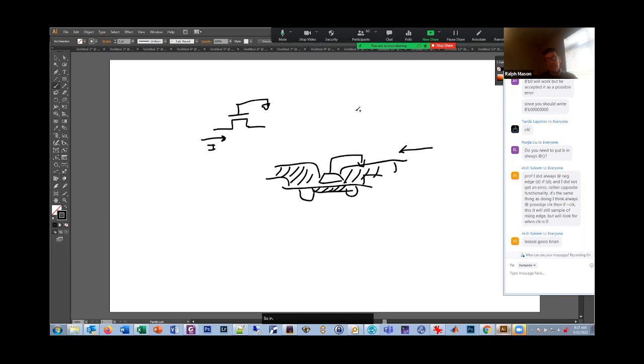So initially, you can think about it, it's kind of like a fuse. Let me draw a fuse symbol, something like that. I can't remember, what's the fuse symbol? Anyway, normally it's a switch that's open. If you put enough current through it, you can force it to close. And once it's closed, this metal physically penetrates under here. It stays closed all the time. So it's the opposite of a fuse. A fuse, you blow it and it's open. An anti-fuse, you blow it and it's closed, okay?